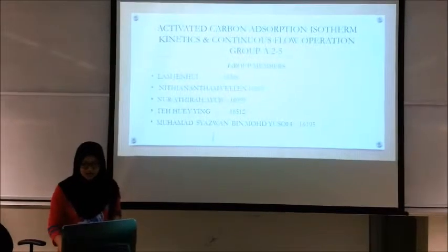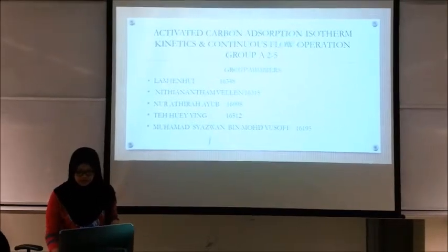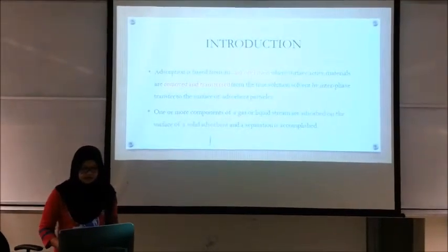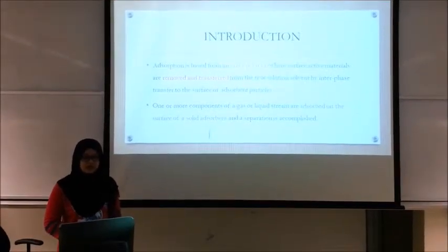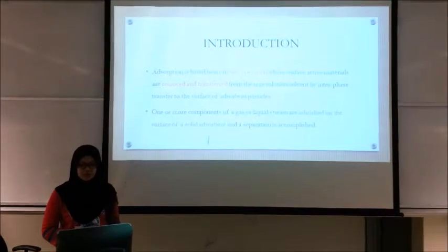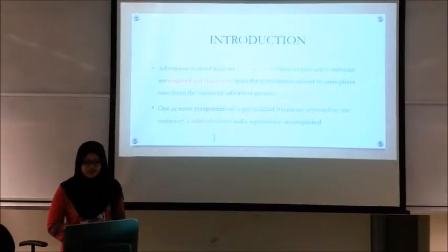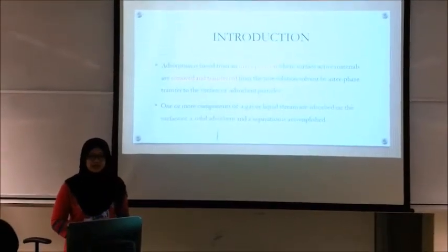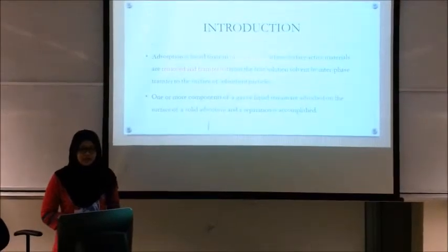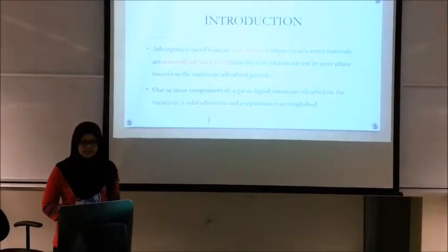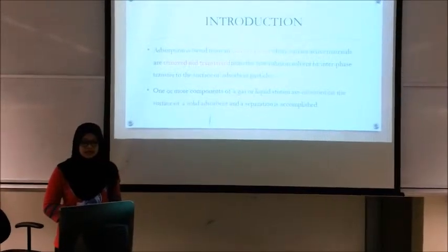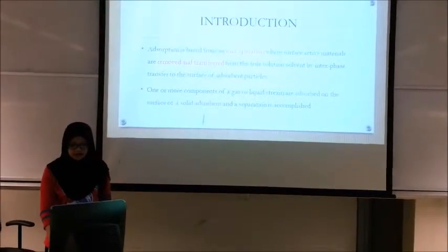So I will elaborate more on the introduction. Adsorption is basically a unit operation where surface active materials are removed and transferred from the true solution solvent by interface transfer to the surface of adsorbent particles. One or more components of a gas or liquid stream are adsorbed on the surface of a solid adsorbent and the separation is accomplished.